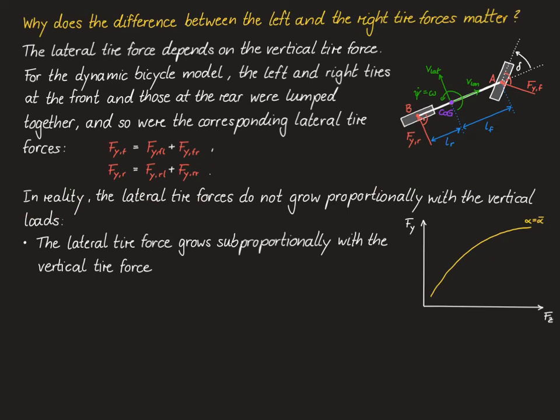As we have seen in the video on lateral tire models, the lateral tire forces do not grow proportionally with the vertical tire loads. In fact, a lateral tire force grows subproportionally with the vertical tire force, as shown in the diagram on the right-hand side. Note that the yellow curve represents the relationship between the vertical tire force and the corresponding lateral tire force of a specific tire for a given slip angle alpha.